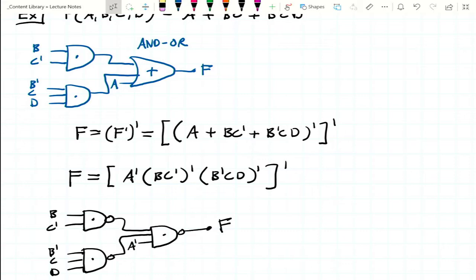So when you're starting to count, we're actually going to build the thing, right? When you physically put the thing on silicon, it's a hell of a lot cheaper to build NAND gates than it is to build AND gates and OR gates. So we convert it to NAND gates to make the final production process a lot more cost effective. That's why. It's also a lot faster. NAND gates, again, because there are fewer transistors, are going to perform a lot faster. You can achieve much higher clock speeds with NAND gates than you can with AND gates and OR gates.